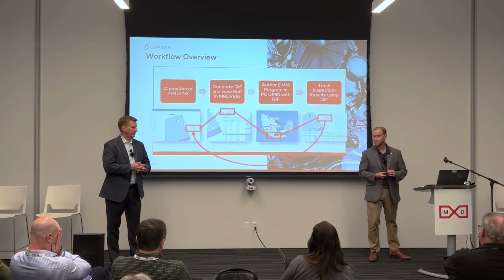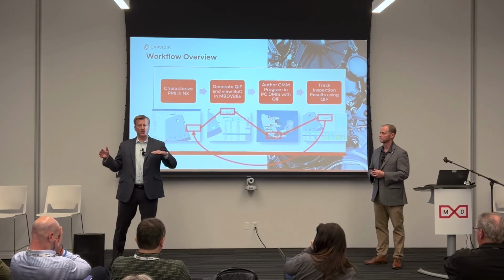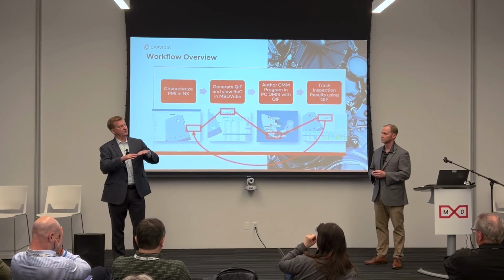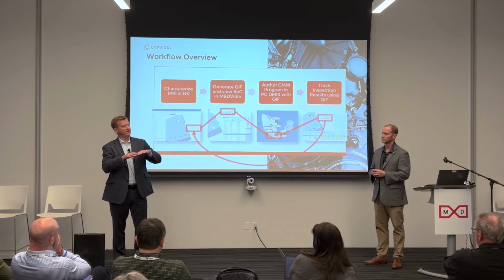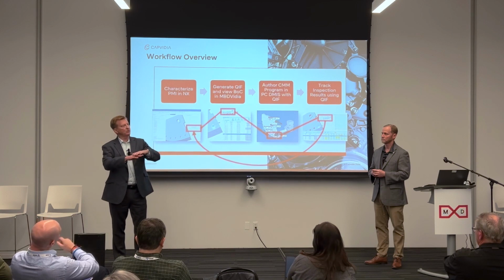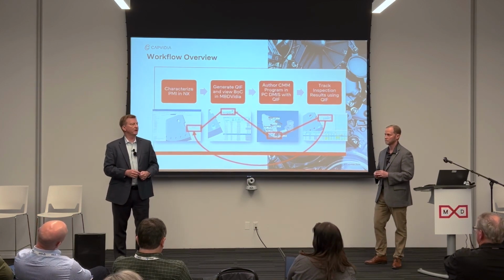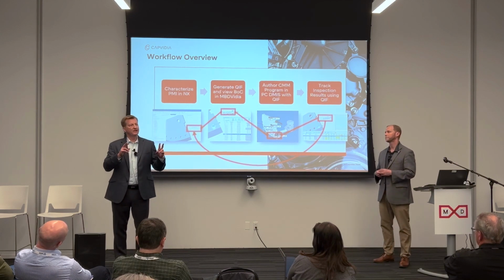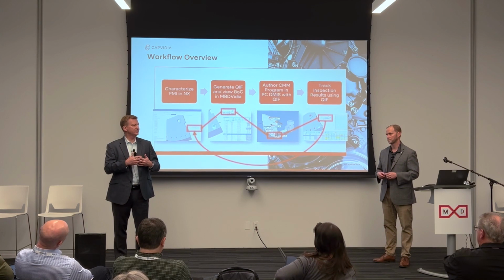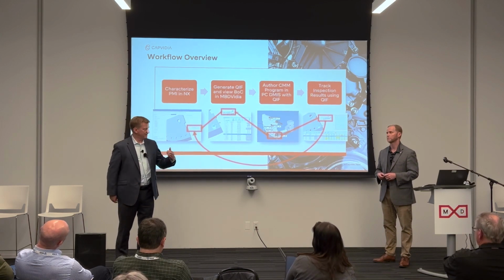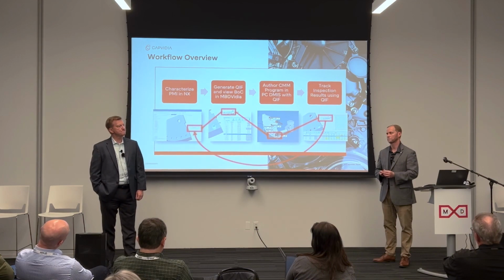The other thing that you get in that regard in NX is if you have patches, depending on the types of products that you're making, and you have continuous or second derivative continuous surfaces, then when you select certain commands in NX, NX will try to find the whole sewn surface and do some other things to help in that regard. So the concept of collections of geometry that things are associated to are known in NX. What NX doesn't have is the manufacturing feature definition of all of those types today.